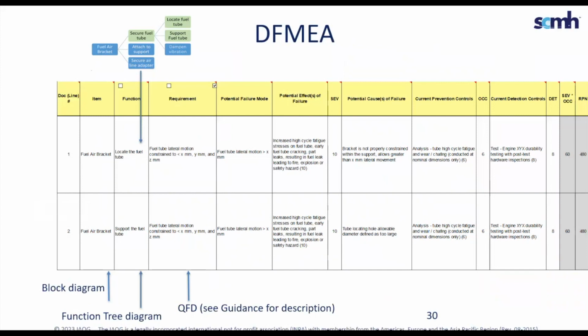Important to reflect on when filling in these two failure modes shown is the high severity experienced for the fuel tube failure mode due to a risk of fuel leak, which could lead to fire or explosion. This will demand elaborated analysis and testing to get a safe installation.